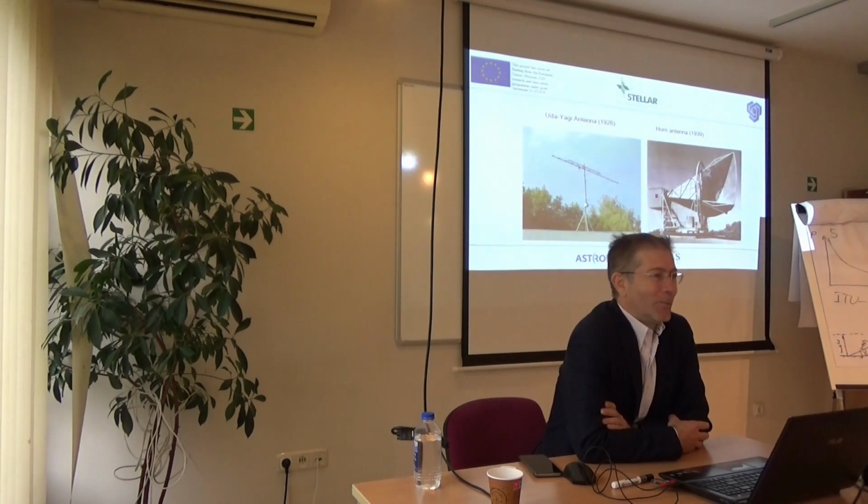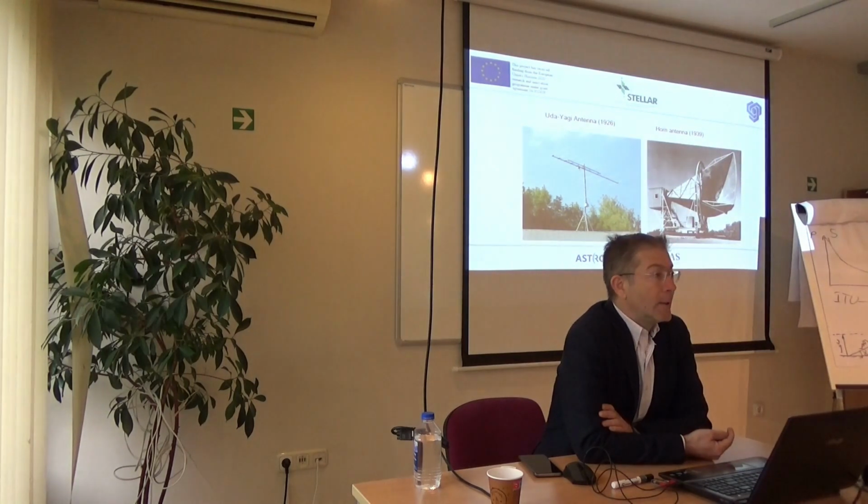The reason is way more prosaic, I think. You need to clear the noise from other signals. Yes, this is the reason. And other signals are usually electrical motors, spark sources, etc. Analog television is very prone to these industrial noises, which are mostly vertical. And if an antenna is designed for one polarization, it is not sensitive to another.